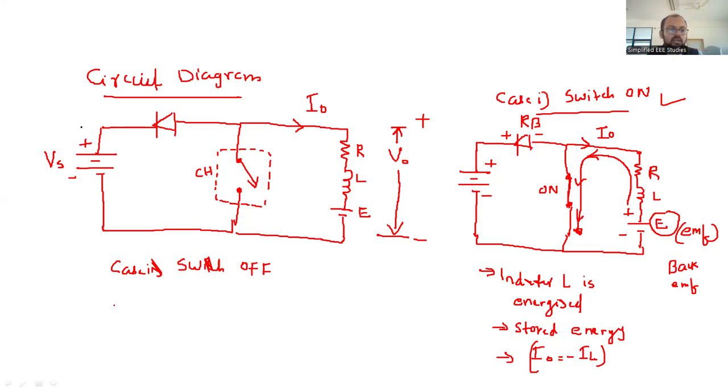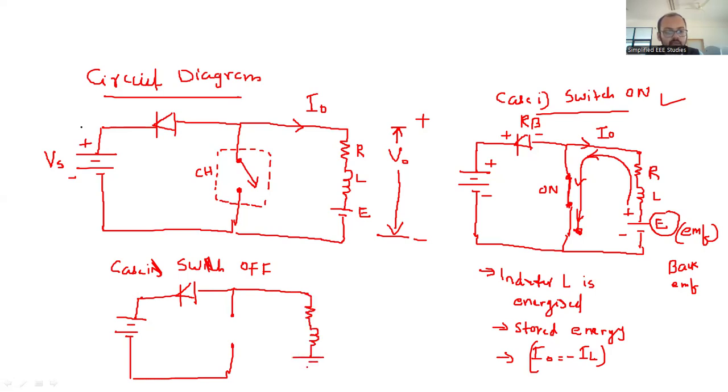Okay. So here already the inductor is getting charged, right? So now what you can do is during the off condition of the switch. Switch on and off will be controlled by the PWM, pulse width modulation techniques, right? So the switch is off. I can mark in this particular direction, in the particular manner. So we'll note down RLE, correct? Yes. Here the inductor polarity will be plus negative minus, right?